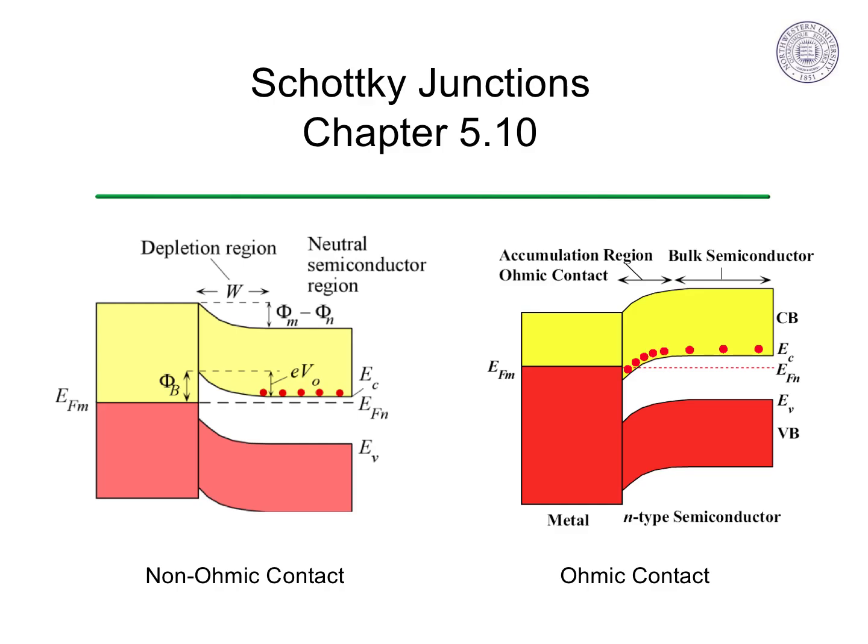In this section, we discuss metal semiconductor junctions, which are important for making semiconductor devices. Depending on the alignment of the metal Fermi level with the semiconductor bands, one can get a diode-like non-ohmic contact, which can be used to make a diode. Or it may be undesirable as it will add additional losses to the circuit. Ohmic contacts can usually be achieved by choosing a different metal or engineering the interface for better band alignment.